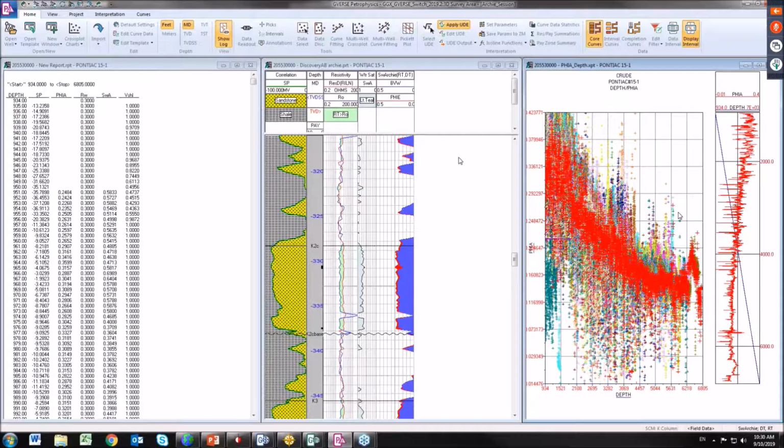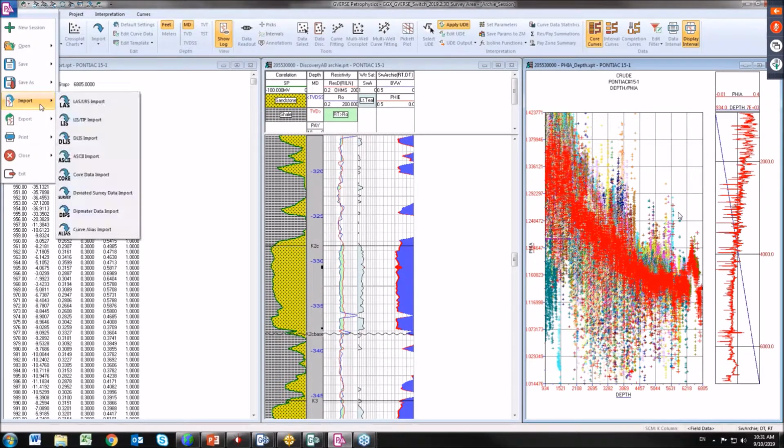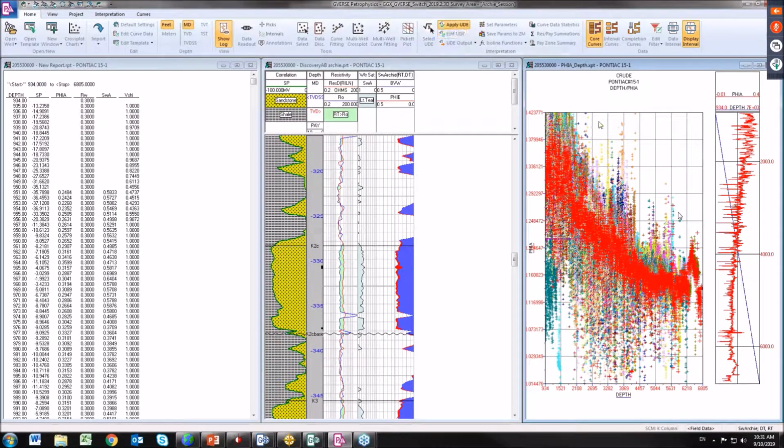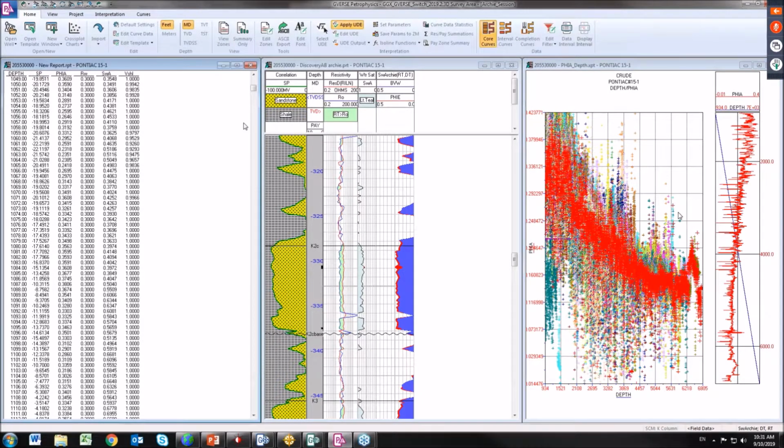We can also create and work with petrophysical analysis. We open GVERSE Petrophysics. It's a very robust tool, our petrophysical tool inside GeoGraphix, to do petrophysical analysis. You can import LAS, deviated survey data, depth-meter data, any type of data that you want to bring into petrophysical analysis, display cross-plots, do multi-well cross-plots, and work with reports to see, for example, in this case, I have an SP, RW, SW report to see the average of that information.